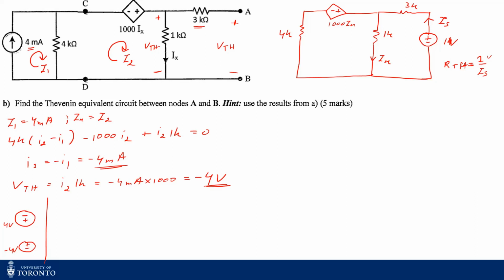I could apply a nodal analysis, because I know the nodal voltage of this node, which is 1 volt. If I assume this to be a ground, now I can just assume this to be my one node. So once I find my nodal voltage V1, my Is will just be 1 minus V1 by 3 kilo ohms. So now let's do the nodal voltages.